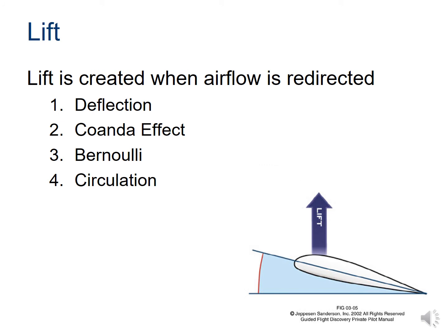Created by modifying the airflow around the airfoil. We will explore 4 contributors to lift: deflection, Coanda, Bernoulli, and circulation. All lift components contribute to lift, but it's too complicated to differentiate, so they're just lumped together as total lift. Total lift is measured directly on the airfoil.